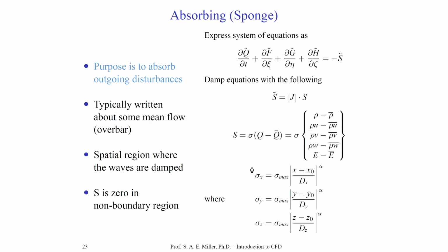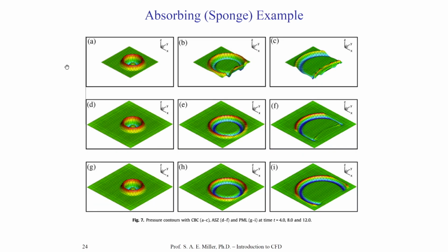Let's look at this graphically. Here's one example of a sponge layer calculation. It's a two-dimensional simulation, as a function of time. These are pressure contours. So the higher the contours in color, the higher the disturbance. The green contour is the ambient. We are disturbing the fluid at one particular point, and you can see that this is a subsonic flow with an ambient Mach number of essentially 0, so the eigenvalues correspond to acoustic waves going in all directions equally, the positive speed of sound and negative speed of sound directions.